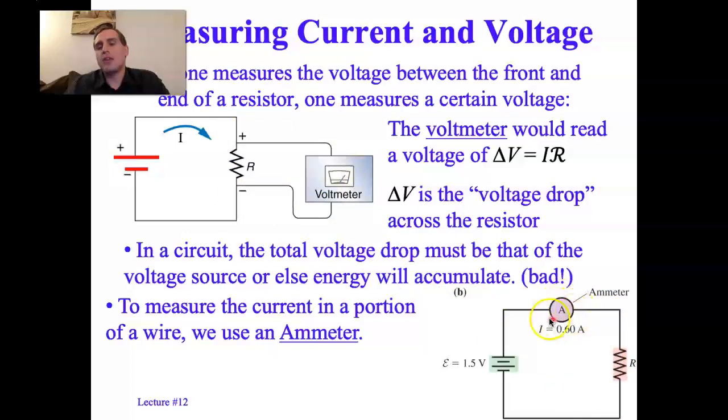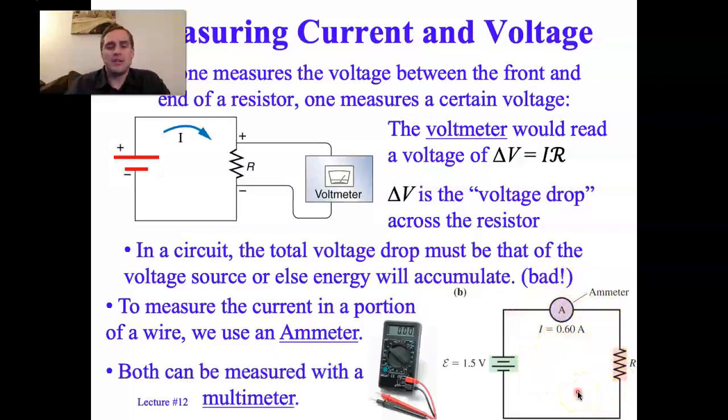In other words, the current flows through that device. Okay? So what we say is we often put voltmeters in parallel to a device, and very little current spritzes through this voltmeter. So voltmeters are generally very safe, whereas ammeters we put in series with the other devices. In other words, we put them in the line of the device.